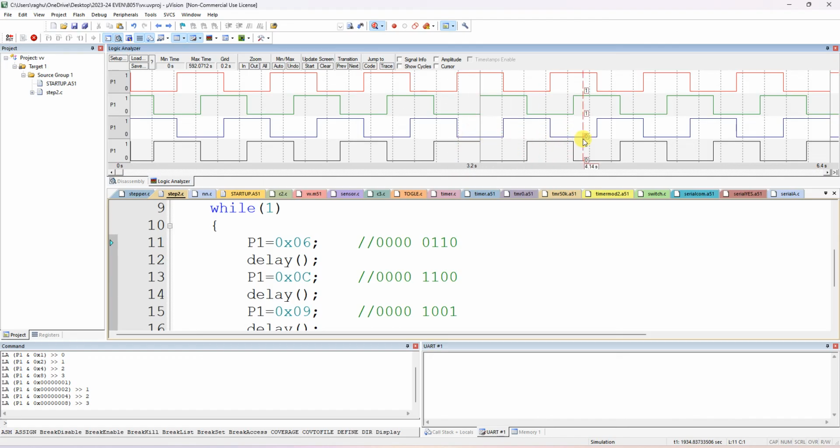If you connect this to the gate, definitely you're going to get the output because you are giving the sequence continuously. If you write a for loop instead of while, after 200 steps, each is one step, at any point of time only two coils are on. You can observe here. After 200 steps, the sequence will stop and the motor will stop rotation. Here we are writing while 1, so it is rotating continuously.